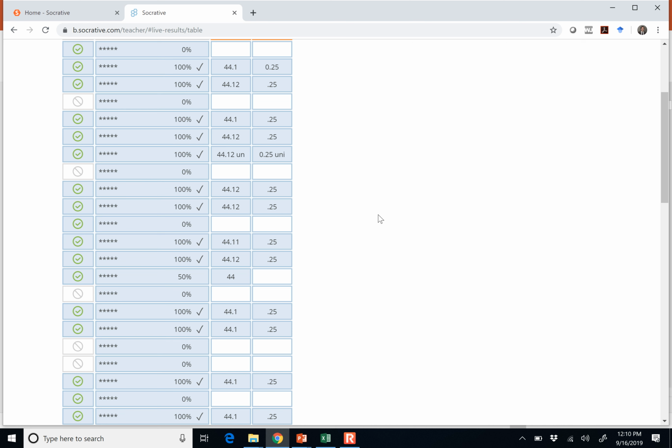There might be a little bit of ambiguity there, but in general, you're probably okay. I'm going to show some results, and it'll probably assure us that the lumped capacitance approximation would be pretty good in the steel case. Just by changing that thermal conductivity, you can see that the Biot number will change drastically. And that will inform you as to how much of a simplified approximation you can take to solving the system.